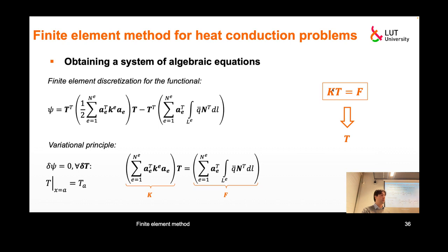And we actually know this K, because inside this K there are element connectivity matrices which we are able to calculate, and there are those matrices which describe how the mesh is connected, how elements relate to each other, which we also somehow know. For any known mesh we can construct those matrices, so we can calculate that if we know the mesh. We know how the element works, and we know how the mesh is composed of those elements. Then we can calculate this global conductivity matrix.